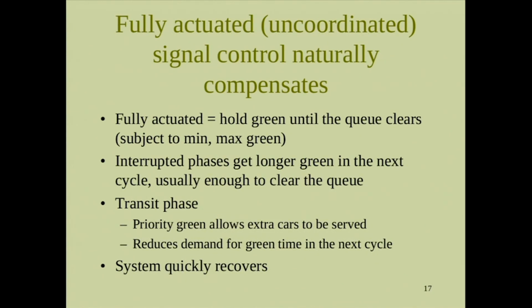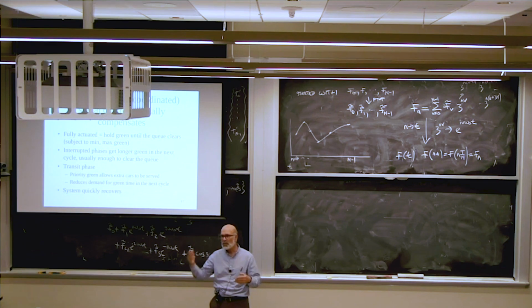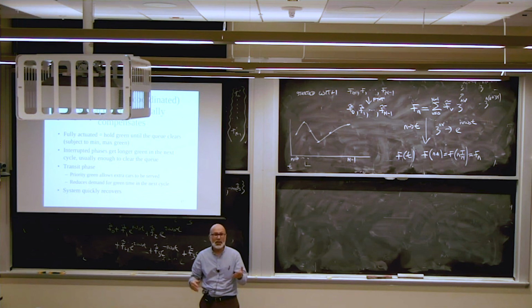And if I interrupt something like that for transit priority, and now there's a longer queue, everybody's been waiting an extra 15 seconds because of this transit priority. Well, when their turn comes up, if they've got more cars, the detector will say, hey, they still have cars. Keep them going, keep them going. Okay, now we finally have a gap. You're over. On to the next one.